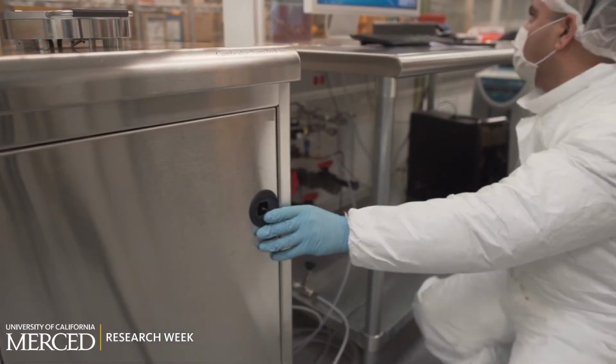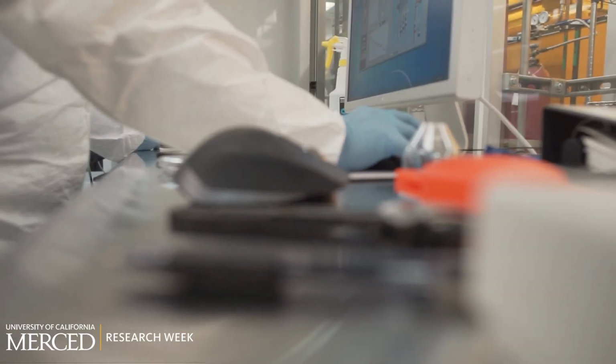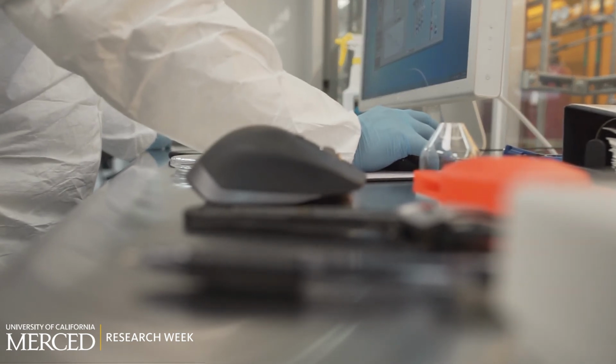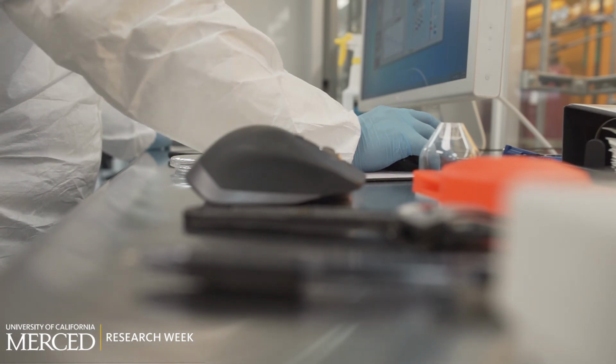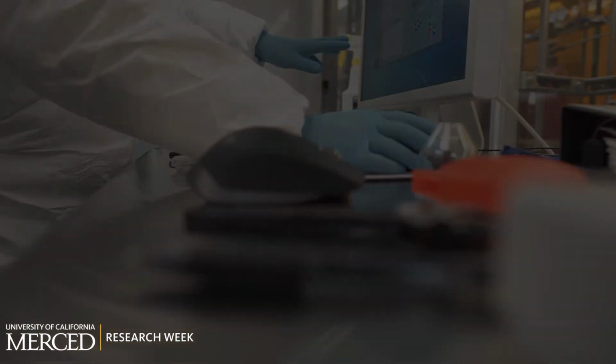Typically, ALD processes are conducted at modest temperatures less than 300 degrees centigrade, and the quality of the growth depends upon chamber pressure and temperature. ALD processes require clean environment and are performed in a vacuum chamber. ALD has wide range of applications in semiconductor industry, lithium-ion batteries, and solar cells.